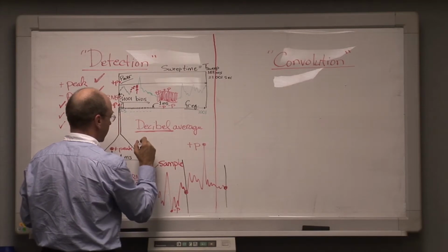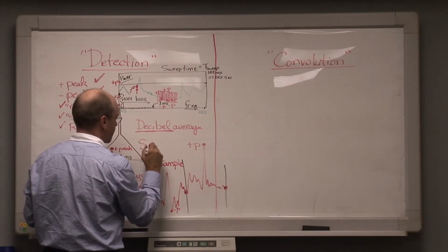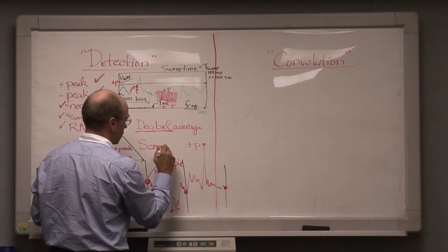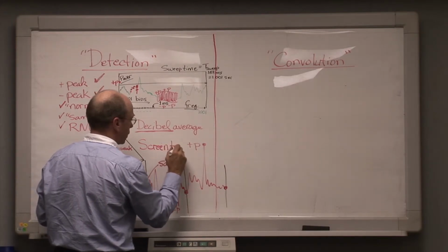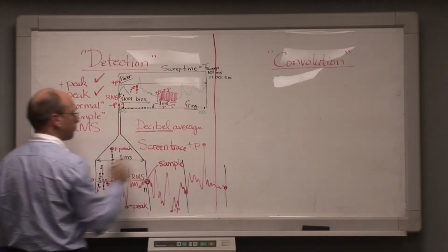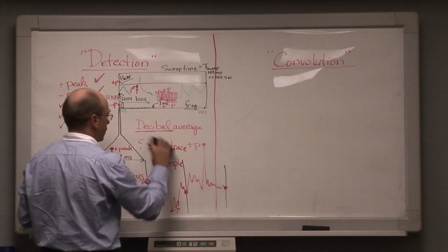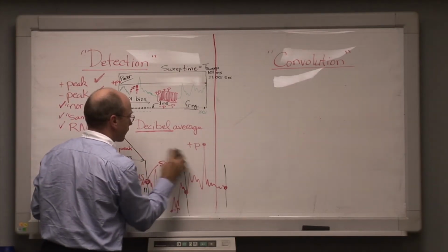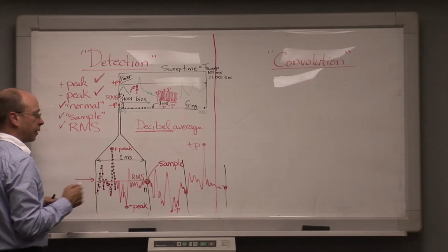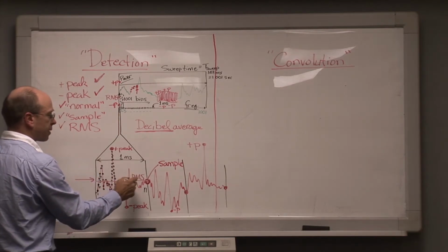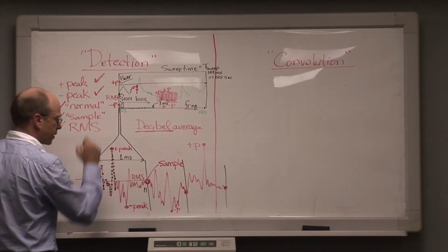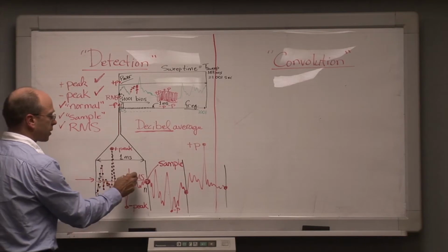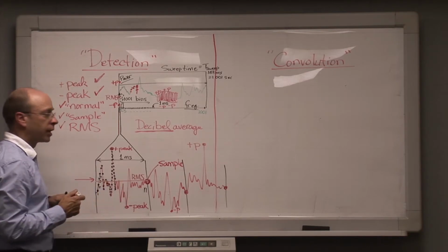And lastly, there is typically a screen averaging or a trace averaging capability that may be slightly different from the decibel averaging in some spectrum analyzer designs. In any event, the only way to get true root mean square power is in fact to have a digital spectrum analyzer with RMS detection built in, or come close to RMS using the video filtering.